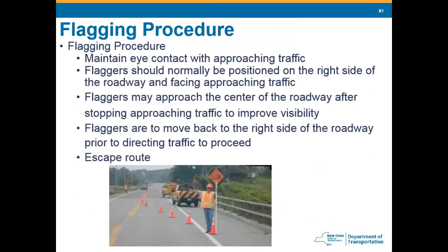Flagging procedure, again, respectful. They need to remain engaged. They need to watch what's coming. They need to stand off, not in the middle of the road, not on the center line. They need to be on the shoulder, on the edge line. They need to be facing traffic. They need to know what's coming.